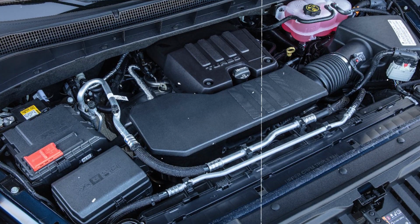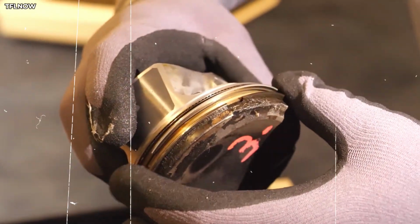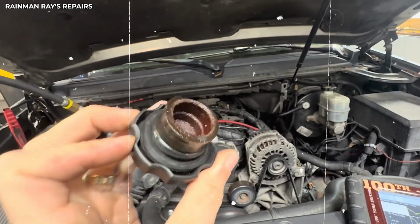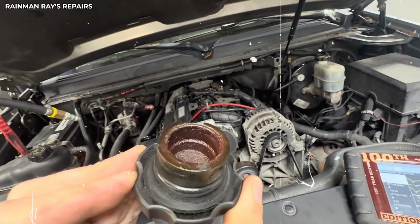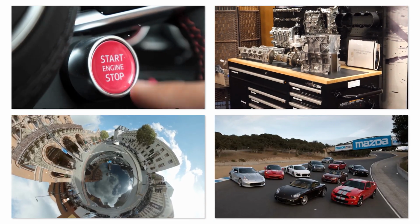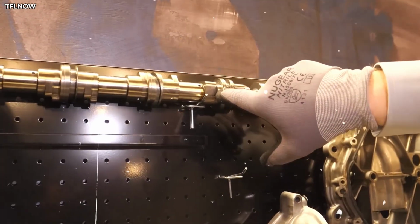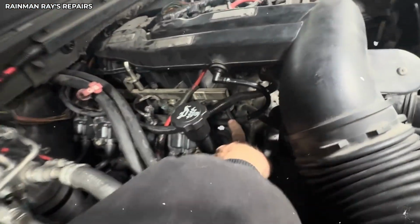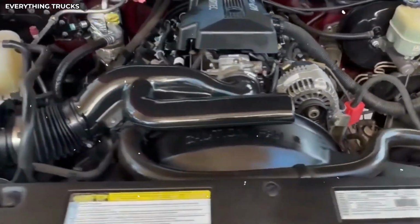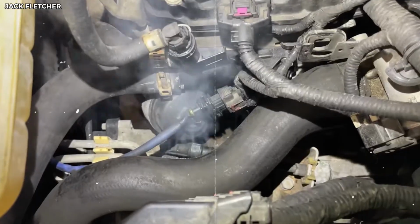The write process takes about 2 minutes. Turn off the ignition, disconnect ForScan, and restart your vehicle normally. The changes take effect immediately. Your throttle response will be noticeably more aggressive from the first press of the accelerator pedal. The advantage of the ForScan method is permanence. The adaptive learning system can still function, but it's working from your new baseline calibration instead of Ford's conservative factory setting. Even if the computer learns gentle driving habits over time, it's learning from a much more aggressive starting point.